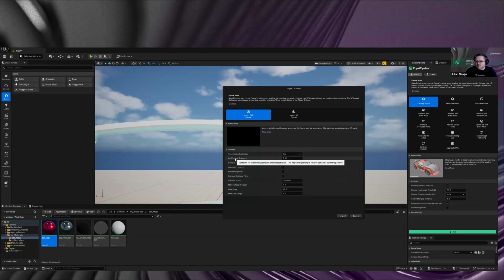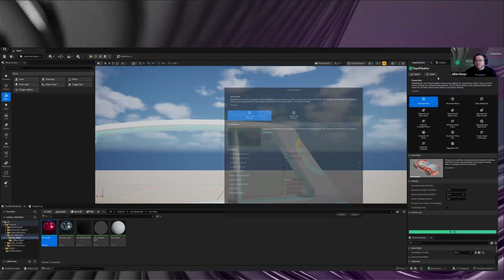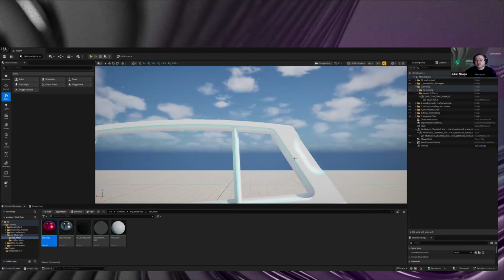Basically, what that does is on the BREP level, it already sews the solids together so that in the tessellation process, we actually get clean vertices. And if we combine that with the T-junction removal, that's actually the best starting point for a clean topology. Of course, also in pairing with the actual surface deviation and resolution you want. And doing that on the door basically gives us a completely different experience, so to say, by merging all these parts together, right?